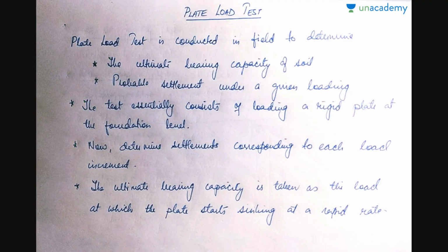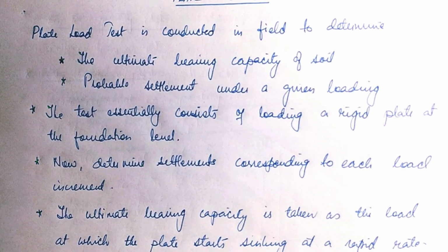And in this lesson, we'll be studying about plate load test. Plate load test is a field test to determine the ultimate bearing capacity of soil and the probable settlement under a given loading.